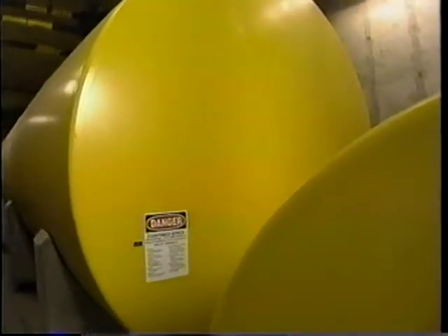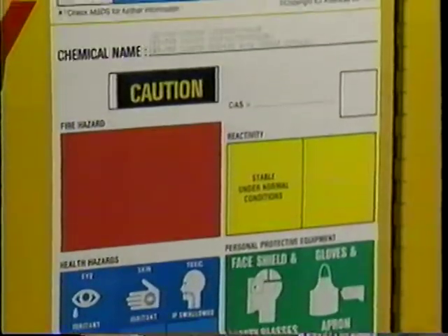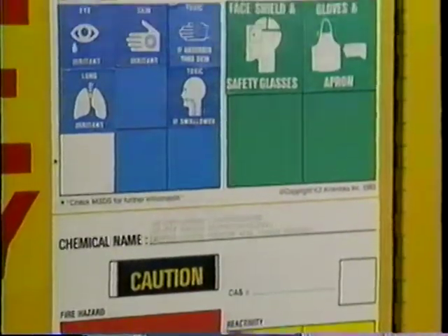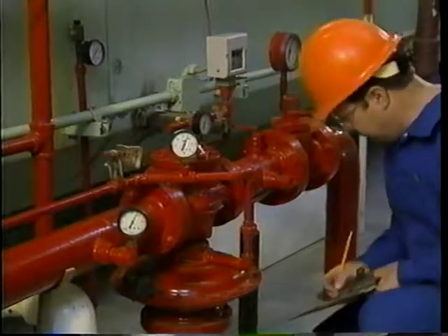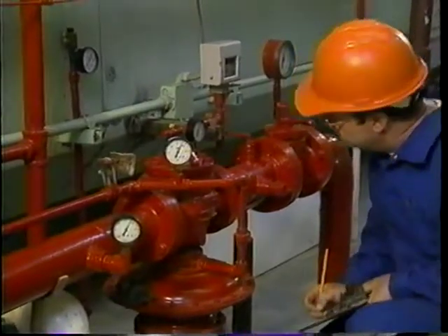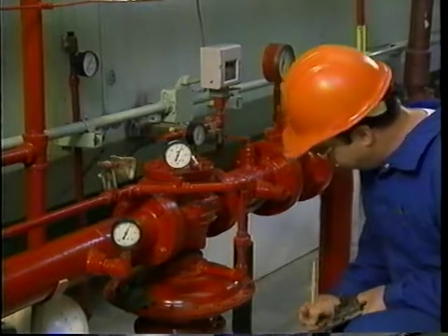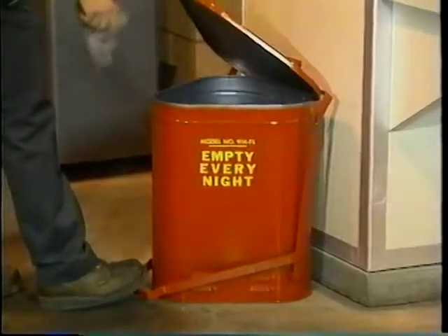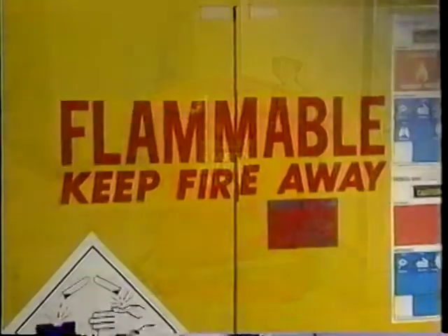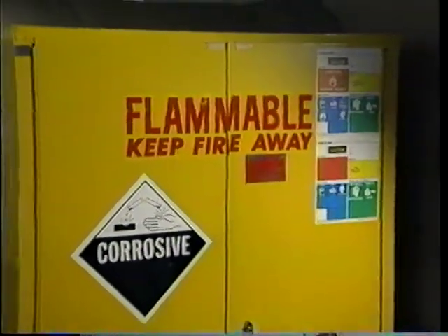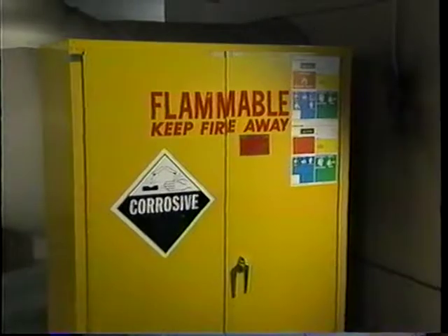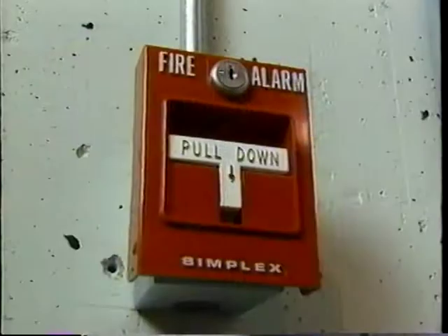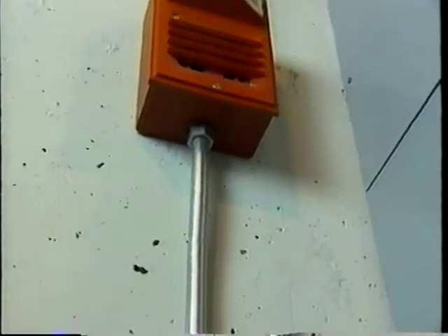Fire safety. The boiler room contains combustibles which require special handling and treatment. Prevention is the best strategy against potential fire hazards. The boiler operator must take the responsibility in preventing conditions which could result in a fire. This includes proper storage of oily rags, proper use and storage of solvents, and immediate cleanup of combustible spills. In the event of a fire, the boiler operator must act quickly to minimize injury and damage.